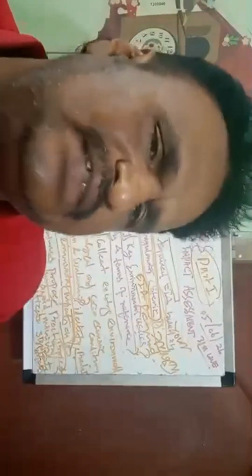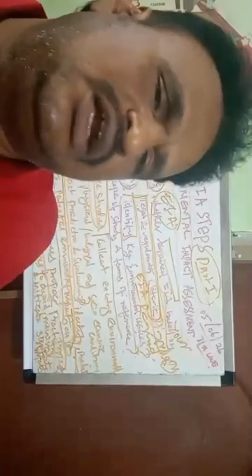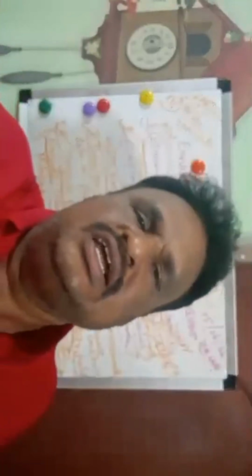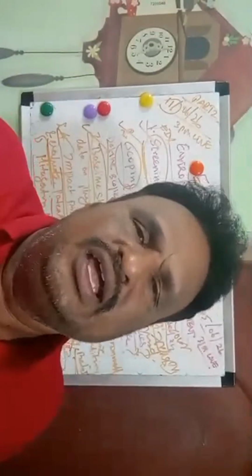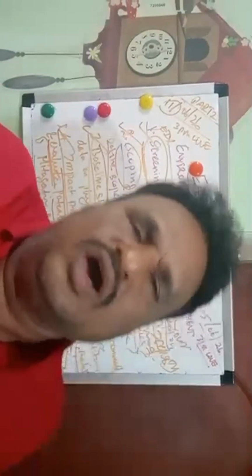First you have to identify the potential environmental impacts. Then you have to give the mitigation measures proposal. Now the baseline study gives the water pH, TDS and so on, this much. But after the chemical industry comes, when you are releasing the water, what will be the impact?